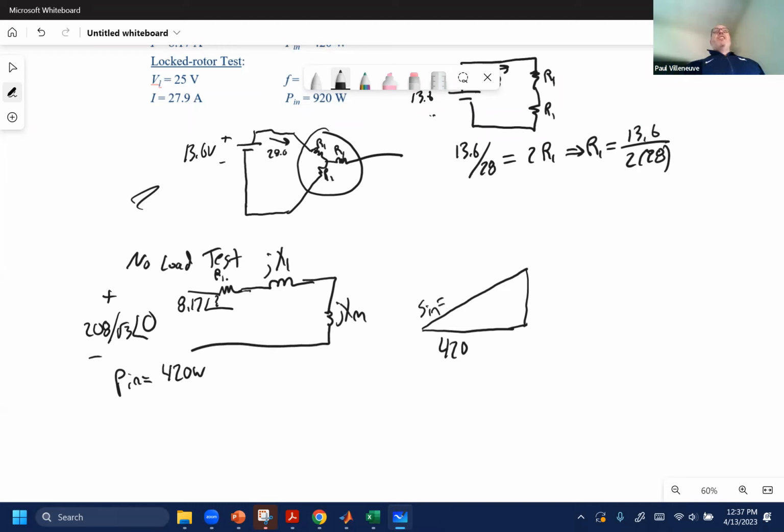All right, so what is S in going to be equal to? Remember, the power that is measured is the 3-phase power. You can't just run one single phase voltage. This machine has to rotate. So when you apply that voltage, that 208, it has to be applied to all 3 phases to make sure that it rotates as if it would normally be operating.